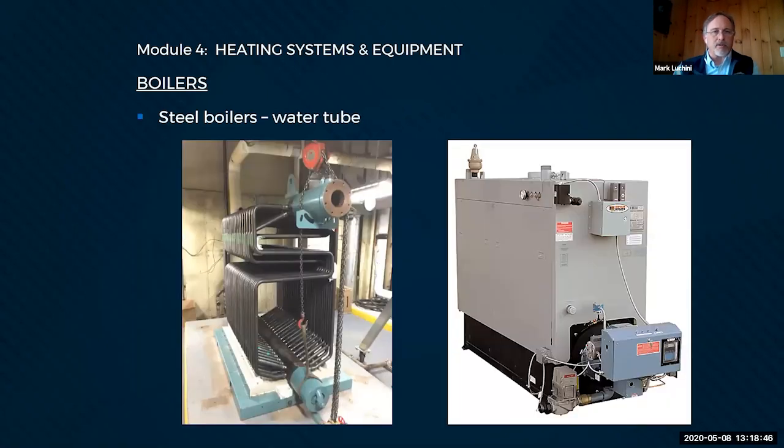A couple of shots of water. This is the interior of a water tube boiler. So basically all they do is build a firebox around it, stick a burner on the end, and away we go, right? The burner would sit right at this end and blow its products of combustion down, back, and across all these tubes and go out the flue.